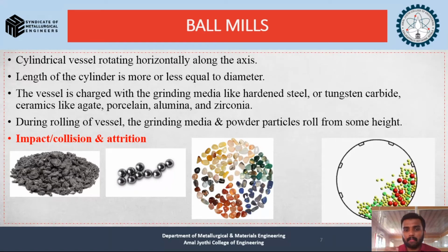It seems like a pebble-like structure. Normally we use it for grinding. You might have seen it in most manufacturing processes. It's a common material, and we have porcelain balls. And what I included in this particular figure initially is titanium sponge. Normally, in order to manufacture titanium, we go for sponge titanium, and that material has to be ground. For that process we go for ball milling, and what we have shown here is a tungsten carbide ball, and this is the hardest material, and whenever we incorporate this kind of material into the ball milling, we will ultimately get very fine particles.